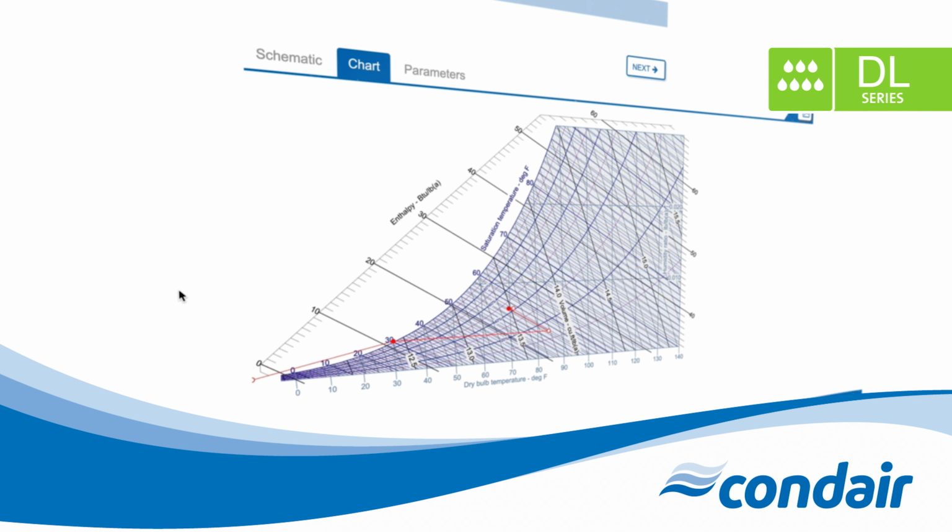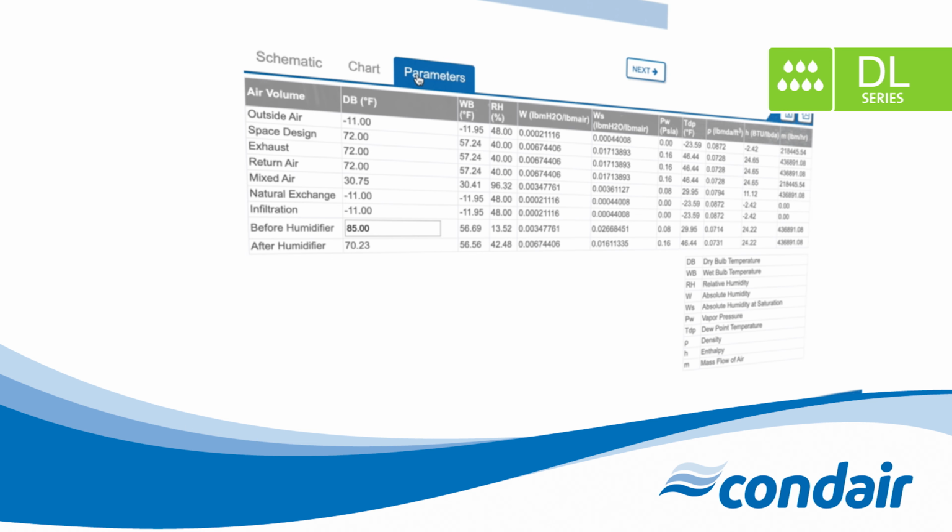The mixed air will enter and be preheated prior to entering the DL, and the adiabatic cooling effect will reduce the temperature and raise the humidity, and then the air will be heated to reach space design conditions. Under the Parameters tab, you'll find a chart with the details of each parameter.